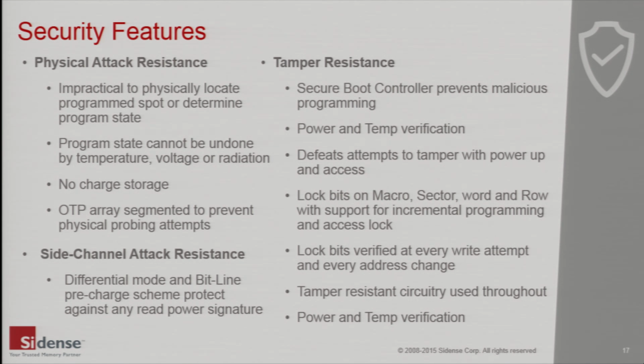Differential read mode and power signature masking techniques are also used to foil any power analysis attacks. And finally, program locks negate attempts to maliciously program the macro. These locks can lock down the whole macro, sectors, or just rows.